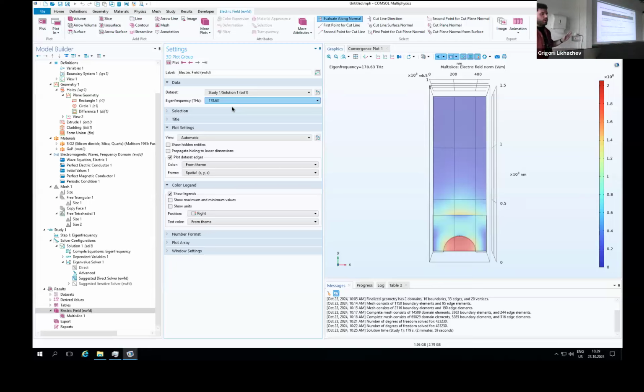Now the question is, what's the length of the resonator? Like we said, of course, the straight waveguide is very long, but depending on the frequency, the penetration depth changes, right? So you don't know exactly how much it penetrates inside this photonic crystal. So what you can do, for a short mirror, is just approximate a constant average penetration depth. I would take it in the middle of the mirror. It's already better than nothing, you know? If it's a short one, it doesn't matter too much.